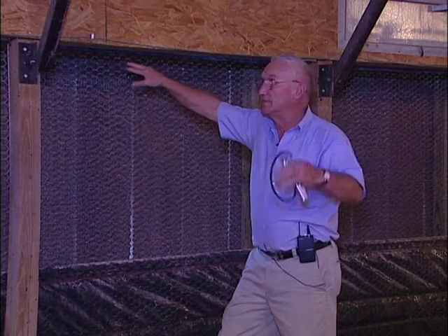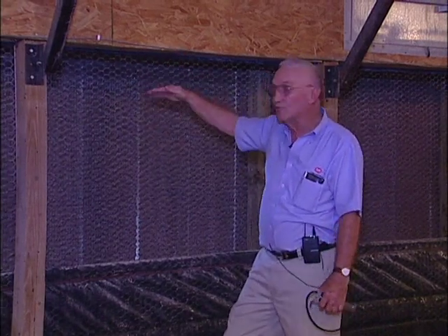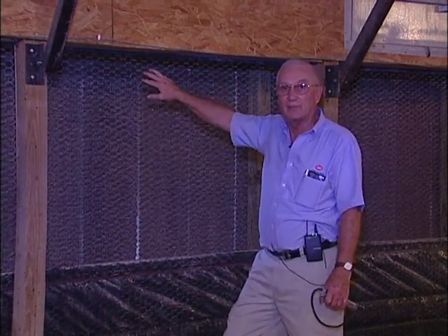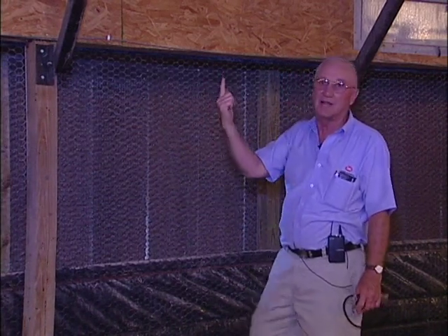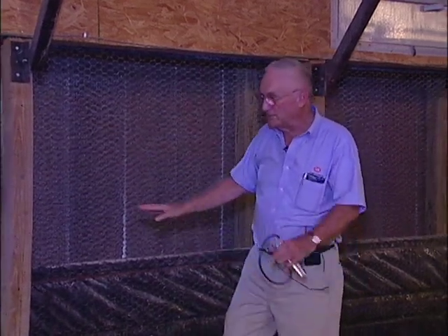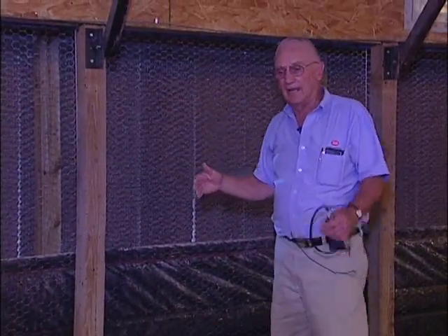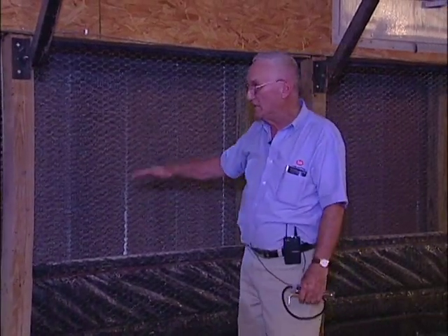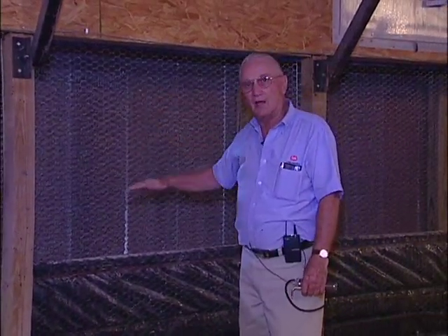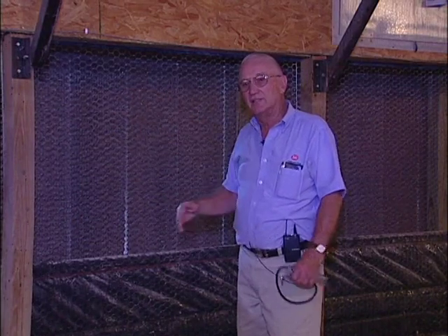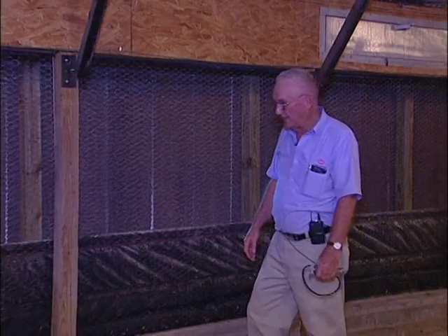When you control this with the height of your pad, it makes the air enter the house without going up to the top. And what happens then, when you get your curtain adjusted properly, as the fan control comes on and off, these curtains will automatically adjust to keep the house pressure the same regardless of the number of fans.